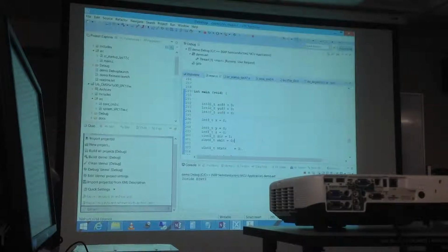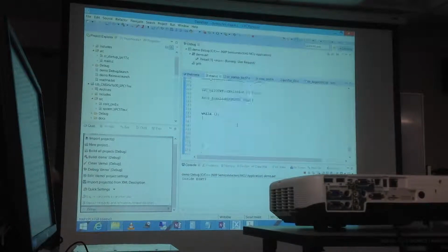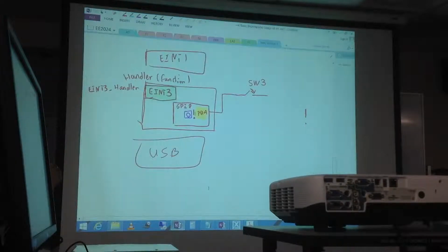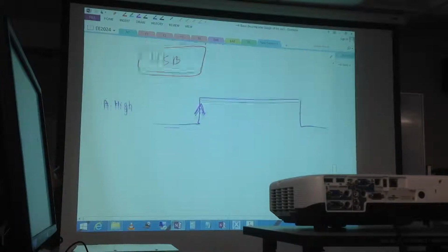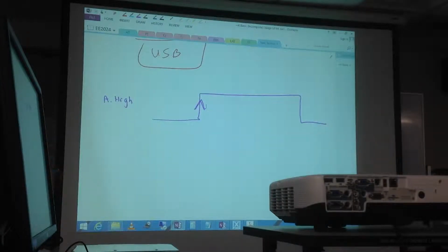We have enabled the interrupt for rising edge, which is here. Rising edge, by default, we mean that the interrupt will be enabled at the rising edge, right? Is that what everyone understands? Well, that is true for active high signal. So this is your rising edge. When you declare the rising edge there, it is for an active high signal.